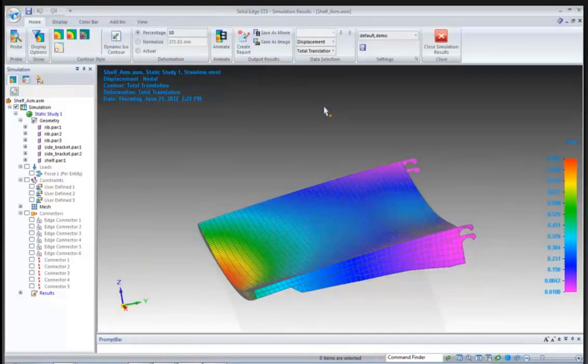It works, and it may work for years, but the problem is you may be spending more money, and your competitors may be coming in and undercutting you because they can make it for less. Because here, in this case, we could use a higher gauge sheet metal, which would make a thinner part, which would save us material costs. So you can not only use this for new parts, but also for parts you're already making to see if there's any room for improvement. Because it's so easy to just click that solve. Once you've got a good model here, and I'm satisfied, I can click resolve and try different things moving forward.